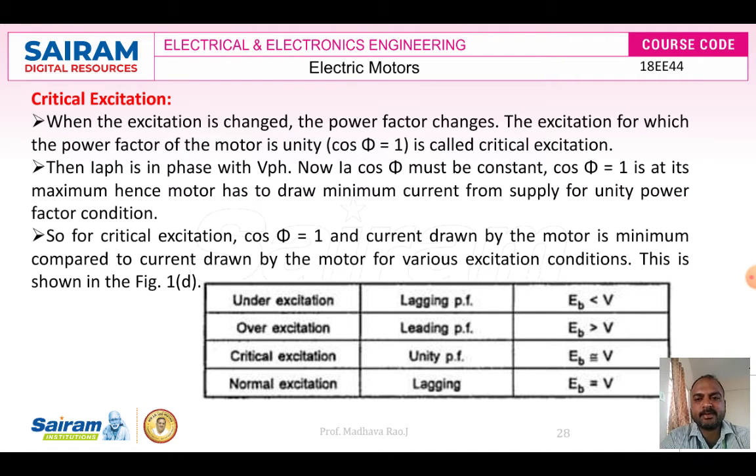The excitation for which the power factor of the motor is unity, cos phi is equal to unity, then the motor is running under critical excitation. So, we can also say if the induced EMF in synchronous motor is equal to supply voltage, then the motor is running under critical excitation.